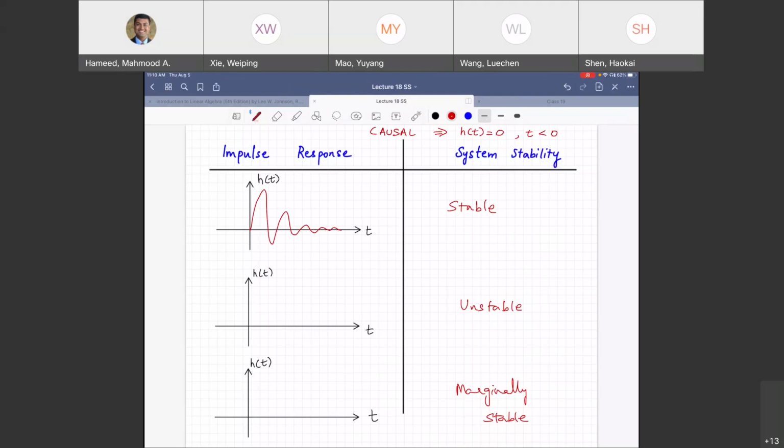Unstable would look like what? Give it energy, and the response grows with time. Think of an audience public setup. There are microphones connected to audio amplifiers with a high gain, with speakers feeding back to the mic. What is happening there? It's a positive feedback environment giving you a very uncomfortable sound. The impulse response looks like this. Even if you tap a little bit, it'll go like a loud sound.